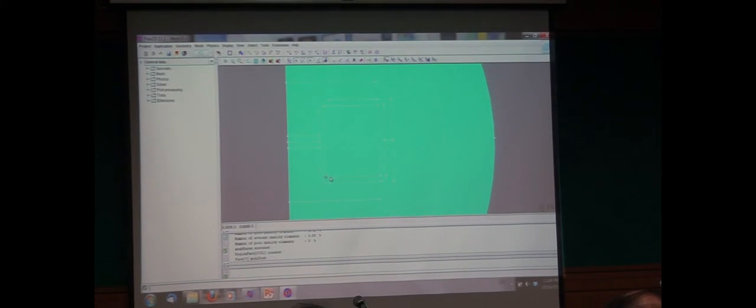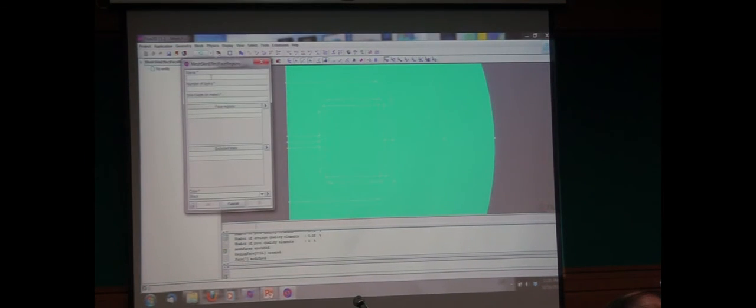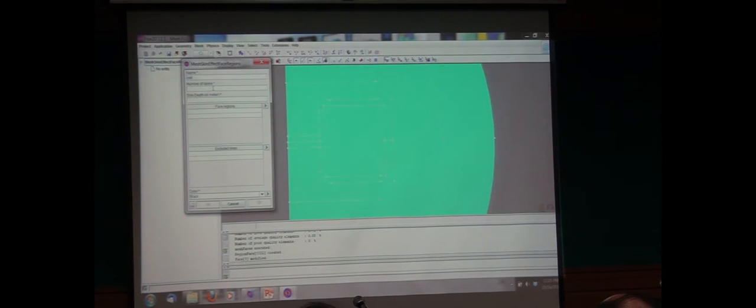So let's see, I don't remember the dimension, it goes from -6 to +6, it's 12. Say for example I was somewhere around 100 hertz, so probably the skin depth would be around maybe 3 millimeters. So let's see, we have the macro, which is right here, that was loaded before. I'm going to call it macro coil. It says mesh skin effect face regions. It's going to ask me how many layers I want within the skin depth. I'm going to put 3. It's going to ask me for the size of the skin depth, so I'm going to put 0.003.